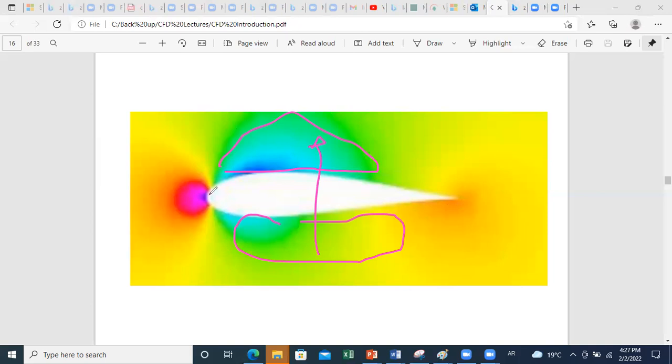They studied how to optimize this profile to create this effect. What is the profile of the airfoil that gives me an overall balance of pressure forces that is up, which will lead to a total net lift that is upward. Whereas if you use a completely symmetrical shape like this, there should be symmetry in your figure, if you neglect the weight effect.